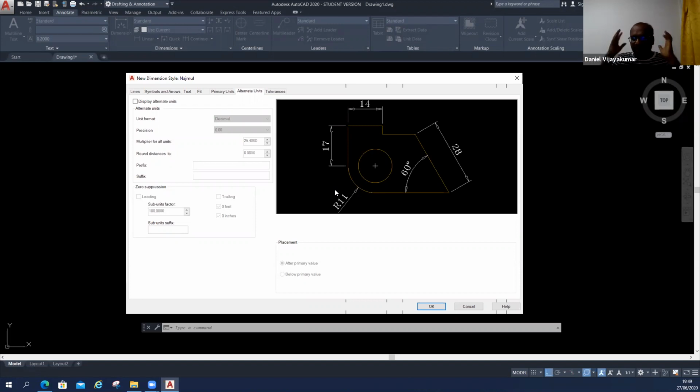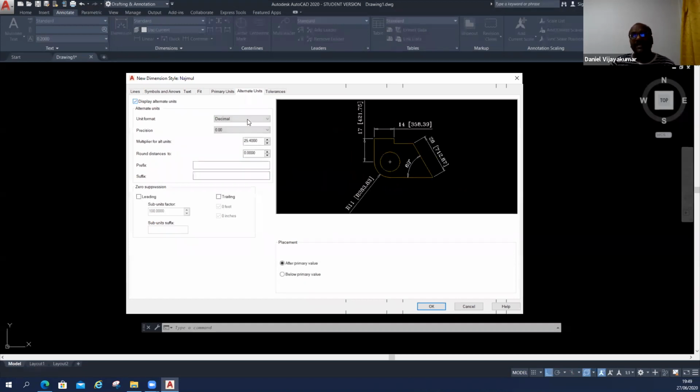It's very difficult to explain your dimension to them, and their dimension is also very hard for us to understand. So that time you can use the alternative value display. For engineering it is feet. If you assign that alternative value, automatically it will show your decimal value for you, and the engineering value for them. If you set it to print out, both people can read at one time.